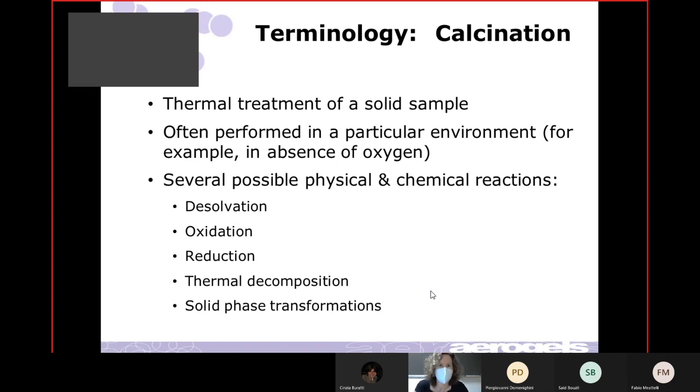And this becomes important when we're thinking about using aerogels for different applications, because sometimes you make a gel and you want to make the gel have better catalytic activity, or you want to make the gel have increased strength. So we saw one example of this in the first part of the lecture, where I was showing the work from Deborah Rolison's group at the Naval Research Laboratory in the US, where they did some annealing. They heated it to strengthen the network so that it could tolerate being put in solvent without having pore collapse. There are going to be other examples in the next examples that I show.